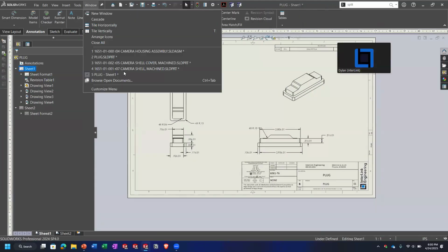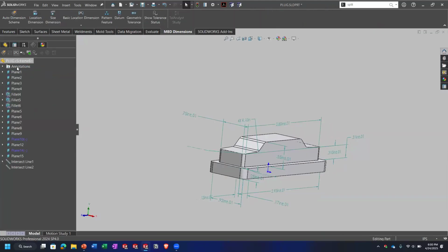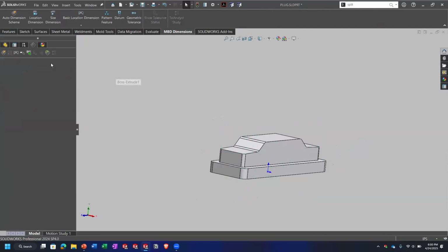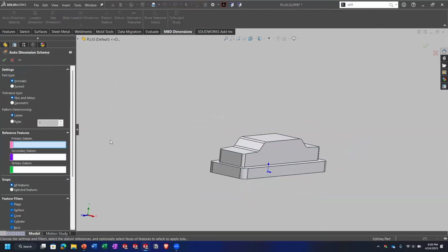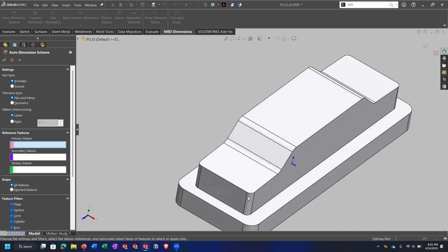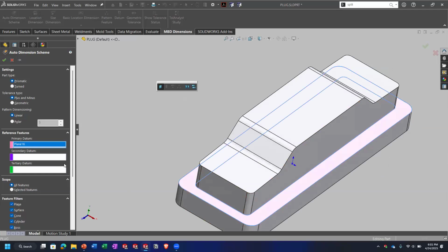Oh yes. Let me. So in this case, because I didn't call out using GD&T, it didn't actually call out datums per se. What I did is I selected what I wanted it to dimension from. So in this case, when I selected my datum right here, I selected this surface. Now, it didn't establish a datum in the sense of calling out datum A. It just dimensioned everything from that surface, knowing that I wanted it from that. But it absolutely could, and it's a good point.